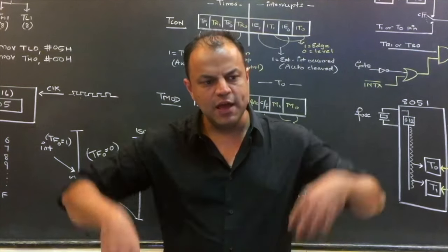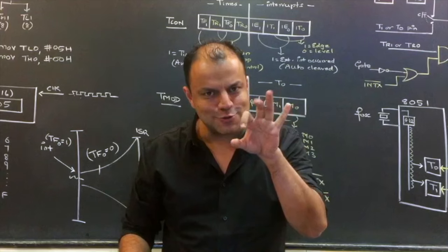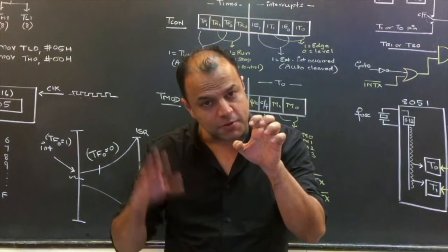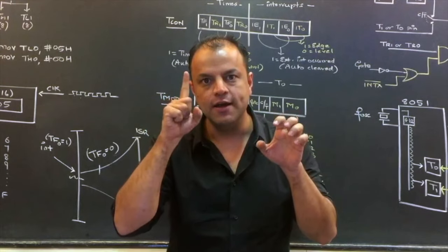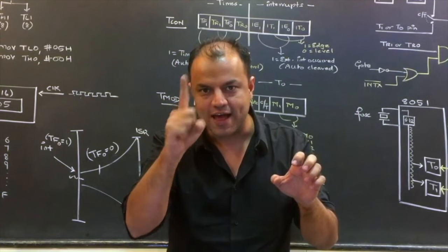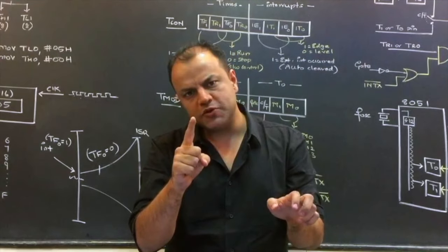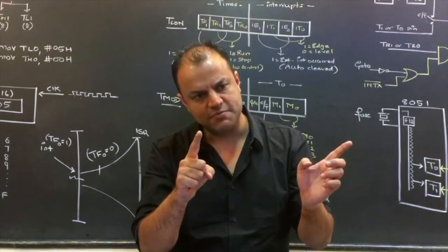So that is why whenever any of those 5 sources that I mentioned are supposed to send an interrupt, first of all they make a flag 1, telling the processor, yes, I have occurred. Now, it interrupts the processor. If processor is doing nothing else, it will go to the ISR immediately.